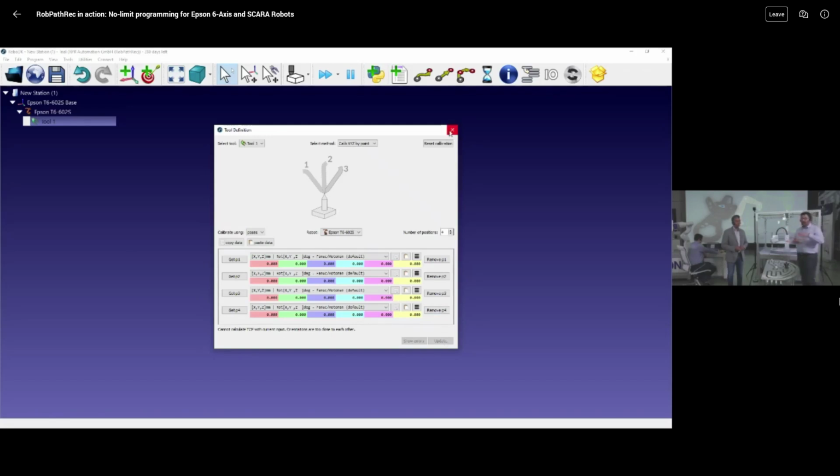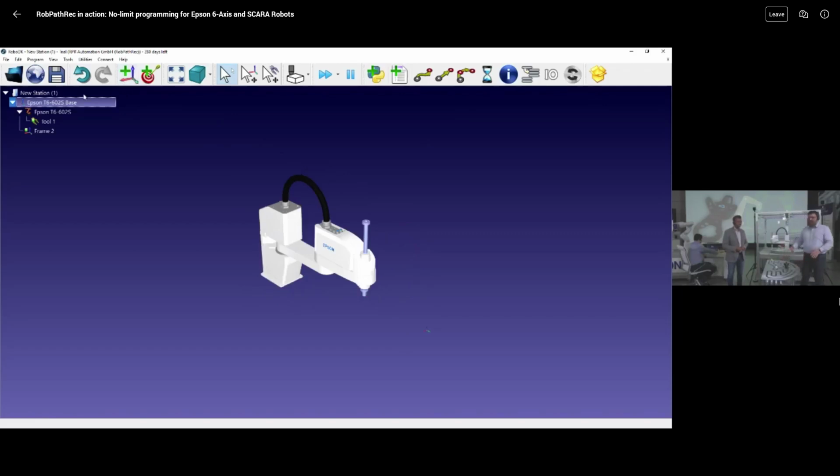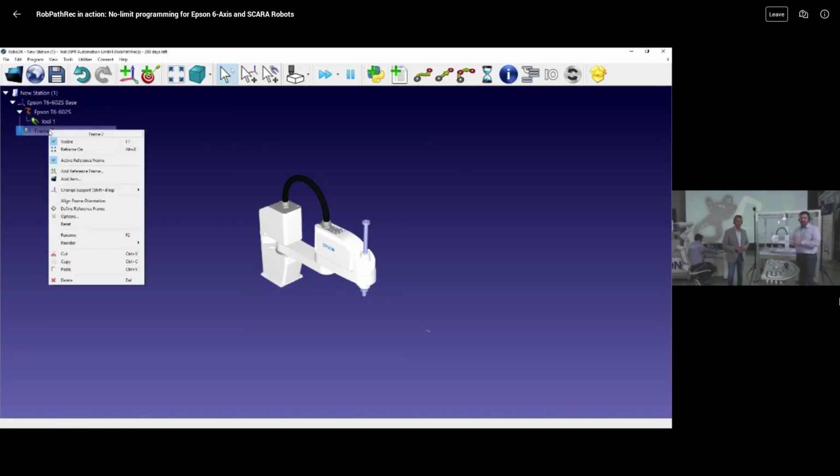As a next one, you have to define the working area. In the Epson wording, it's called local. We call it user frame, but it is the same thing. So we are talking about the definition of the layer where we will do the job. Balázs, I think, already added a user frame. There is an additional built-in function in RoboDK for defining this working area.